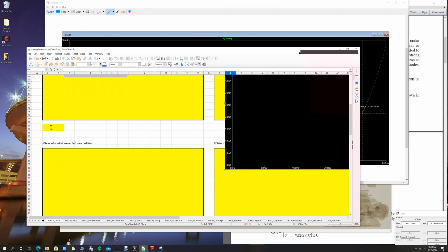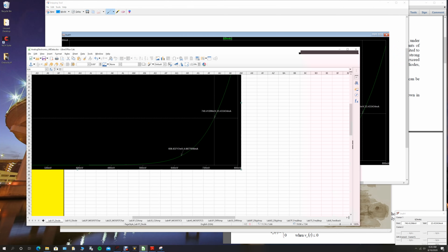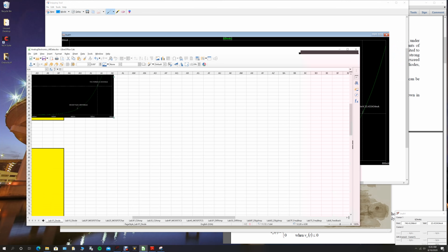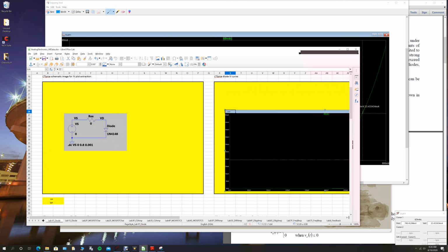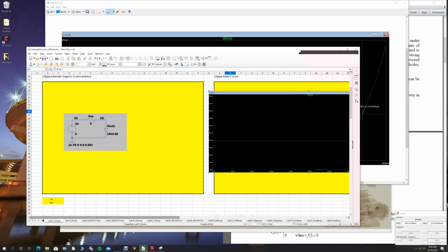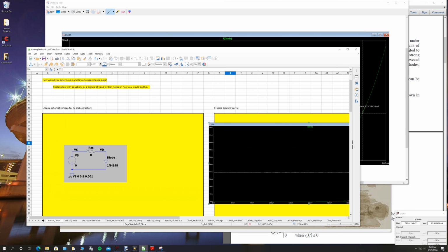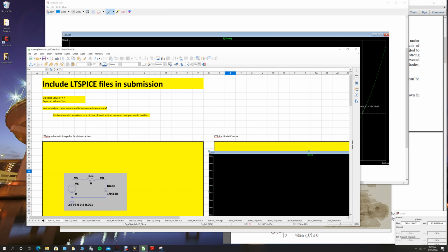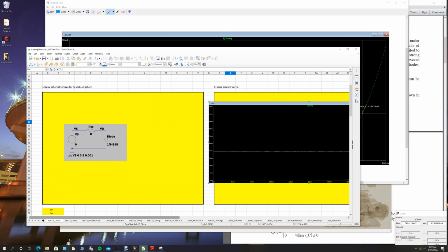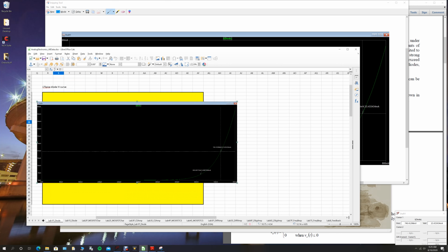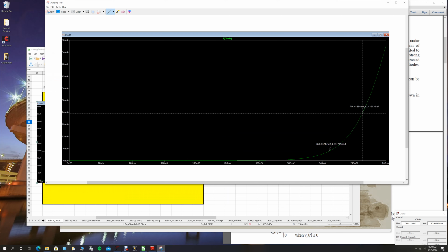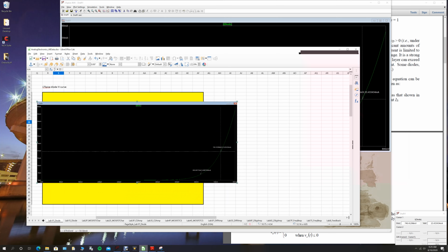And you can resize the picture if you want, so it fits in the box. Up to you. Okay, looks good. And from this data we can figure out N and IS based on the methods from the previous Prelab part. You can use the 2 data point method. You could use the zero bias to figure out what IS is. So let's have a look and see what that gives us real quick.